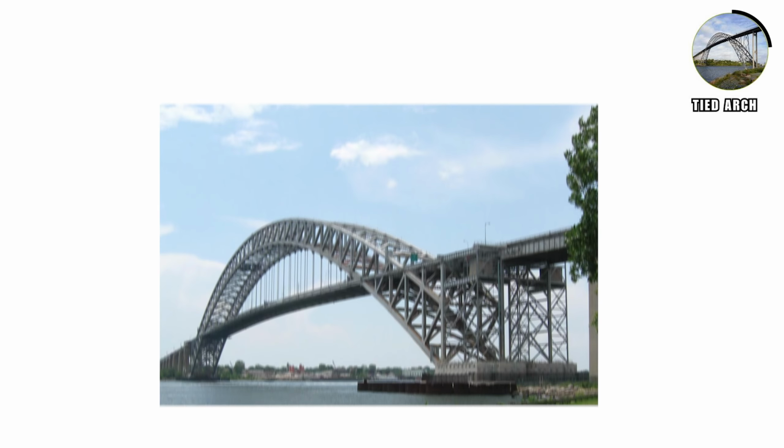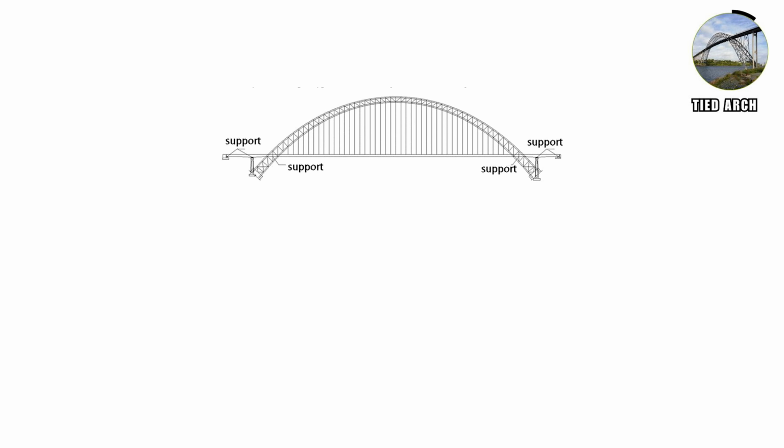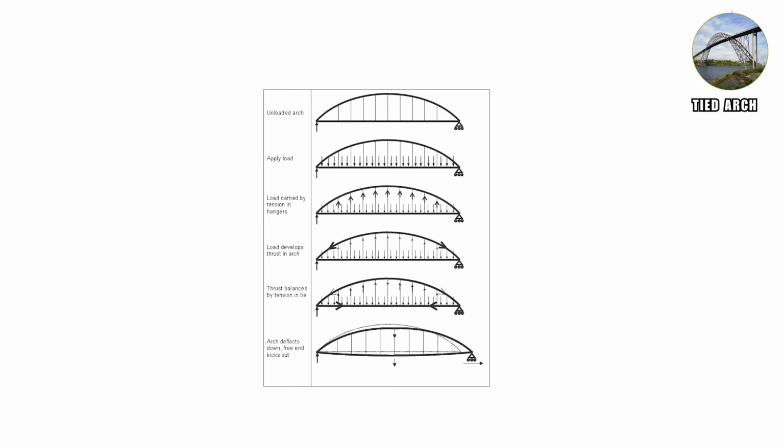To distinguish an arch from a tied arch visually, look at the supports. If the end of each arch sits on a spindly pier or some other structure that seems insubstantial against horizontal forces, they're probably tied together and it's not a true arch.